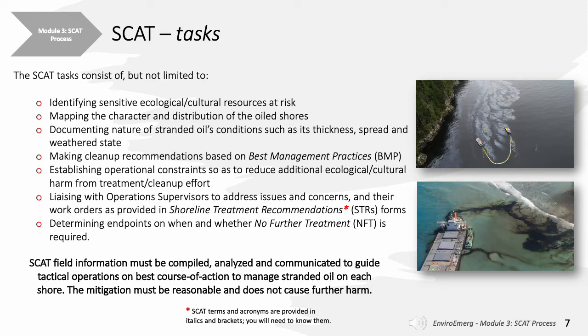Then you are out in the field on an oiled shore, mapping the character and distribution of the oil, such as documenting the stranded oil's conditions, its thickness, spread, and weathering state. From there, you're making recommendations on cleanup based on best management practices. As well, to establish a net environmental benefit, you're establishing operation constraints so as to reduce additional ecological and cultural harm from the actual treatment or cleanup efforts.